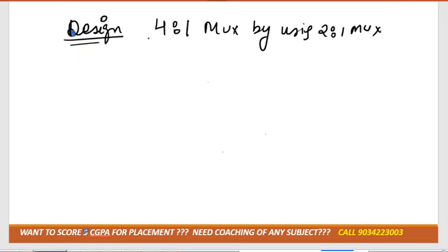So this kind of question can come in your exam. Technically, it is known as mux design, so they can ask you any designing. They can ask you to design 8 is to 1 mux by using 2 is to 1 mux, or they can ask you to design any mux with any mux.